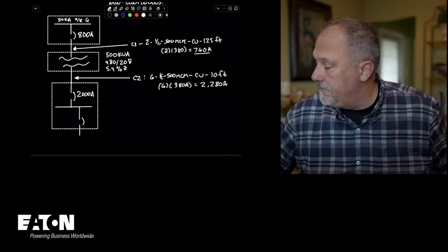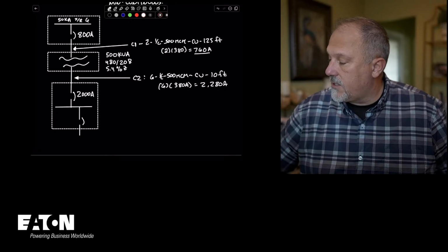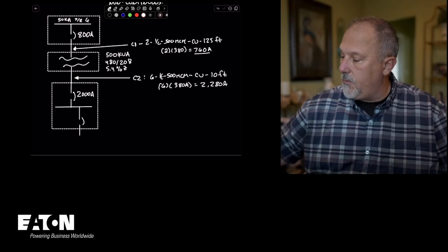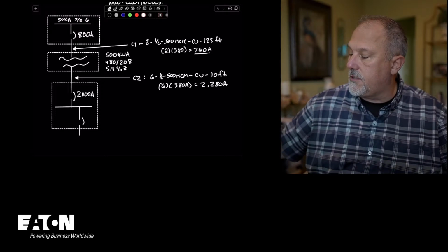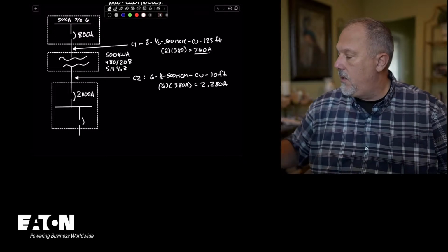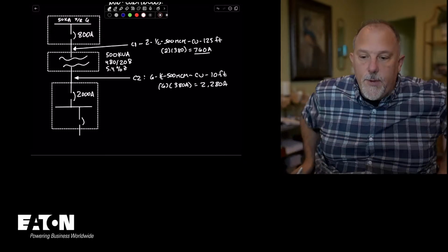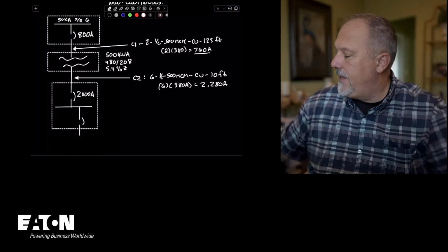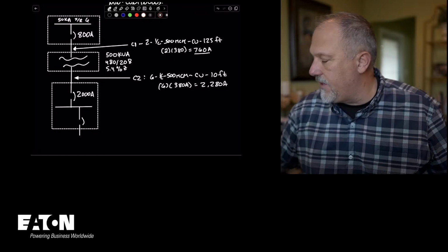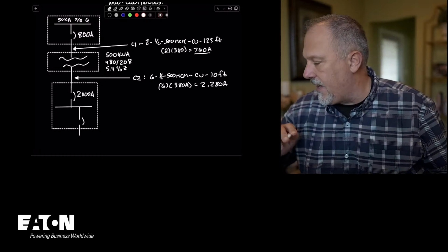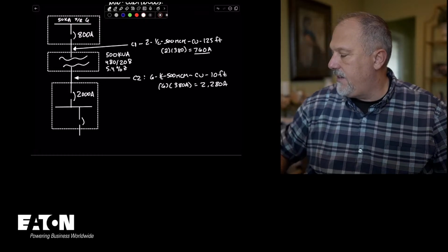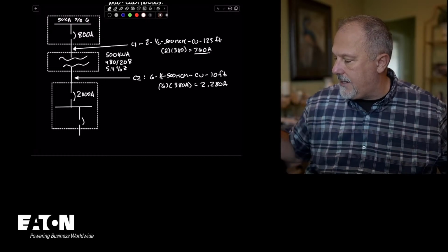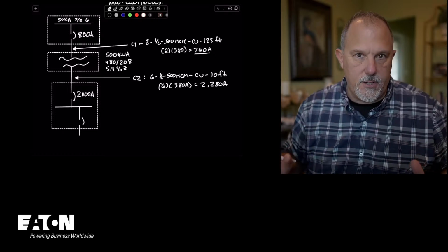We have a system. We have conductor 1. We have 50 kiloamps. We have an 800 amp breaker. We have conductor 1, which is 2 single conductor, 500 MCM. Oh, look at that. Yeah, I see what you're saying. 1 reel. Now I get what you're saying. All right, so we have, and then on the secondary, we have 6 single conductor, 500 MCM, 10 foot, and I have 125 foot. Anybody disagree with the lengths or anything like that? Are we golden? I'm feeling good.